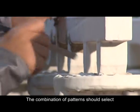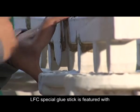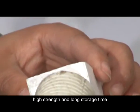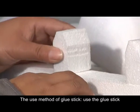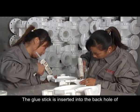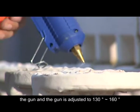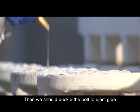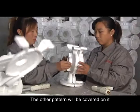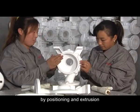The combination of patterns should use LFC special glue stick. LFC special glue stick is featured with convenient use, quick solidification, high strength, and long storage time. The use method of the glue stick: use it with the glue stick gun. The glue stick is inserted into the back hole of the gun, and the gun is adjusted to 130 to 160 degrees. Then we should squeeze the trigger to eject glue. The glue is ejected on the pattern, and the other pattern is covered on it. High strength can be achieved by positioning and extrusion.